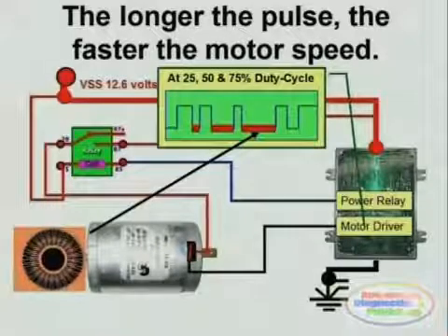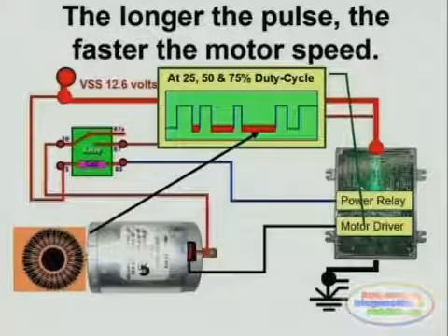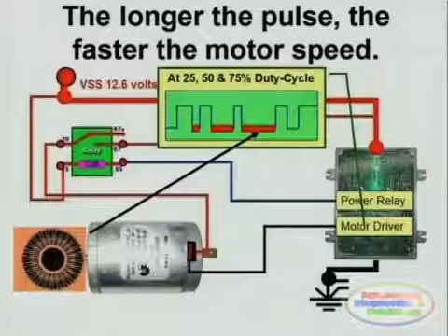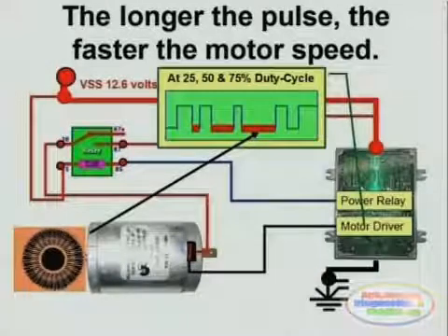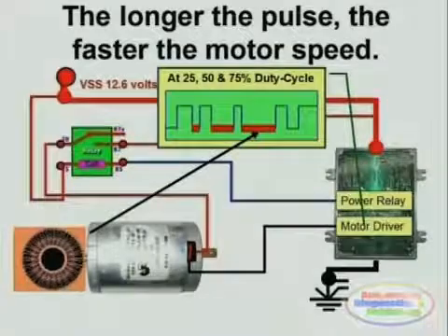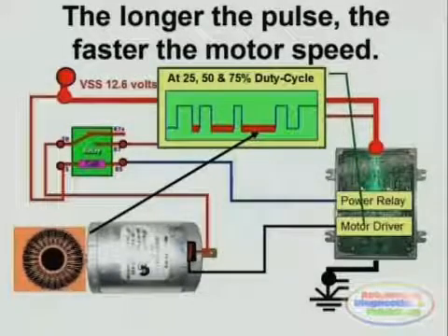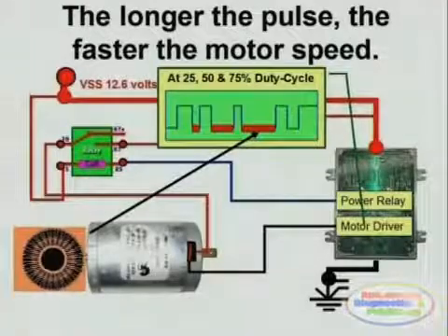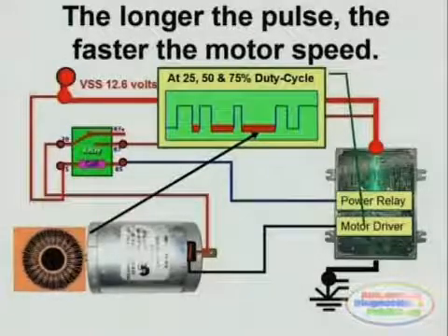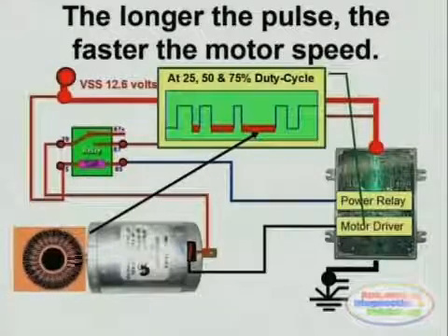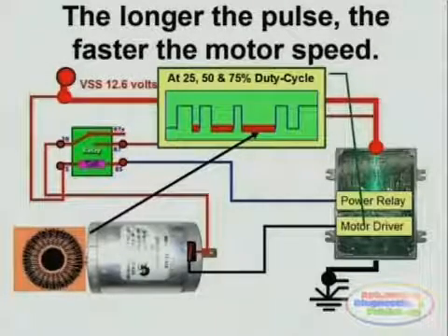The output of the controlling circuitry is going to be determined by the width of the pulse that is applied to the base of the transistor that is doing the controlling. This pulse is modified by the microprocessor through its internal circuitry, and the microprocessor, through the transistor driver, determines the speed of the component being controlled.